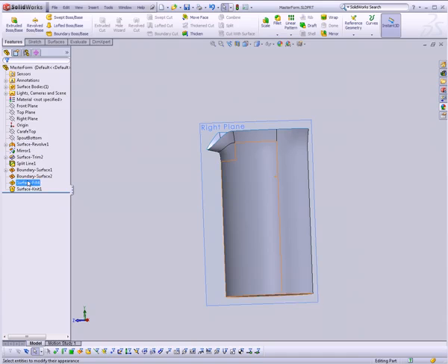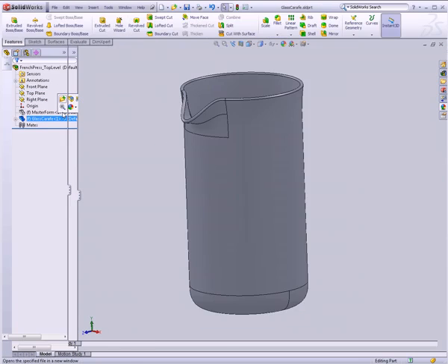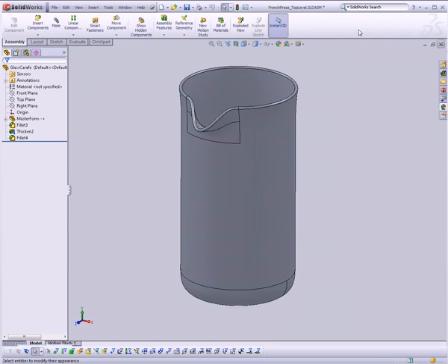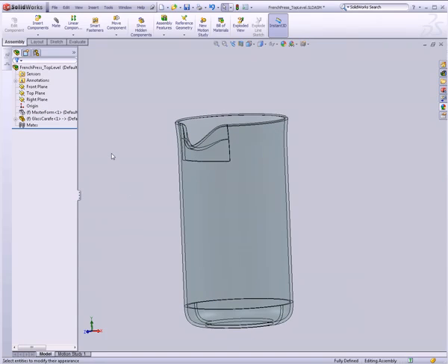So there's no point in adding complexity to this model just to add that surface in our master form. It's better to go back to our assembly, go into the actual final part, and add the fillet there. That's just going to keep things clean and simple as we continue to work. So without further ado, I suppose we should just move on.